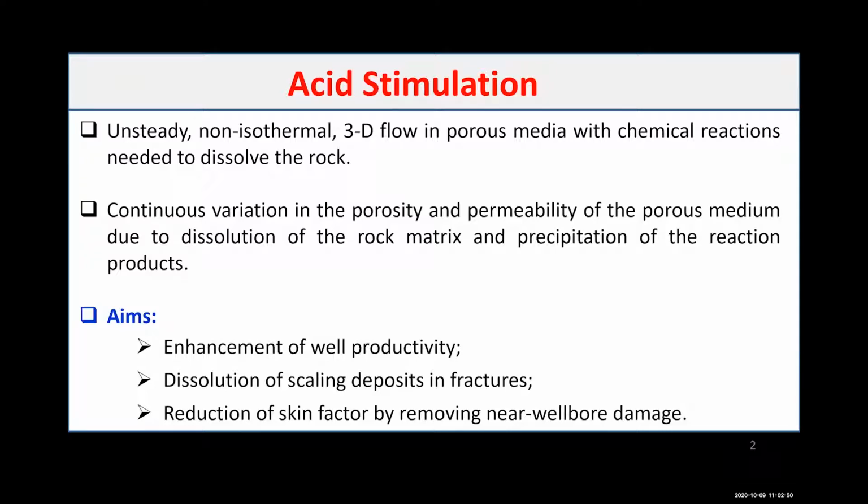And most important, we are injecting the acid inside the formation, so we have porous medium flow, governed by Darcy's law. And as I'm talking about acidizing, we are talking about chemical reactions. The acid will dissolve the rock, resulting in variation in porosity and permeability. The acid reacts with the rock and dissolves some of it, so we expect an increase in porosity, which leads to an increase in permeability.